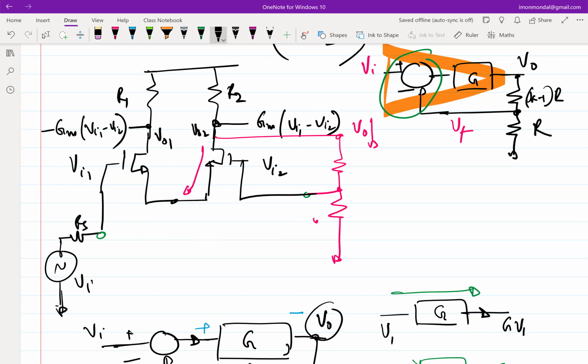The other thing, now the second thing, is finding out the gain of the loop, like loop gain, or GH or L. So we can do the similar thing, right? So we break the loop. Let's say this is the place to break the loop because, again, no loading. So I will break the loop here. I'll apply a test voltage V test, and I'll observe V return.